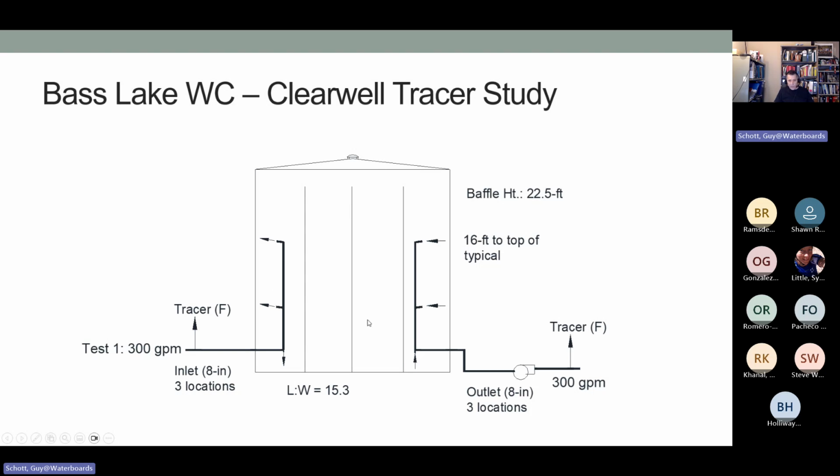Years ago, we had a tank where they had a bypass, and we did a step dose. Looking at the results, it didn't make sense. So I kept asking the operator, do you have a bypass? No. They finally said, yeah, we have one, but it's been closed. I said, can you check? They said, it's closed. After a few times calling him back, I said, go check it and make sure it's closed. He found the valve was open. So they had a bypass going on.